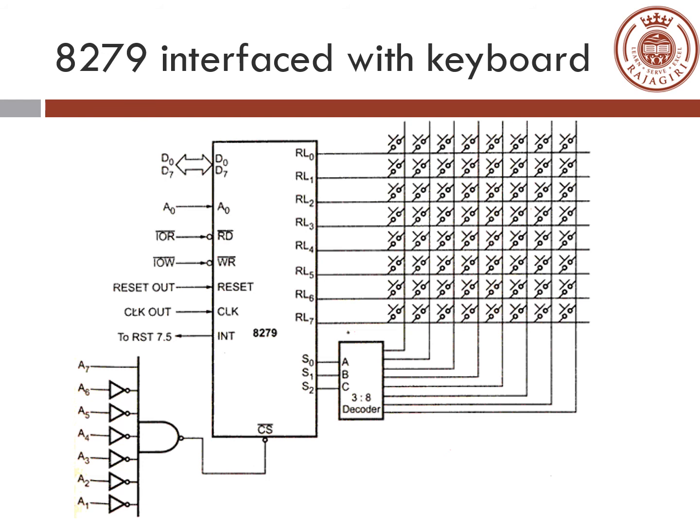The chip select is selected by means of the address lines A1 to A7. So if A1 to A6 is 0 and A7 is a 1, then we generate a signal to connect to the chip select. So that's the interface to the keyboard.